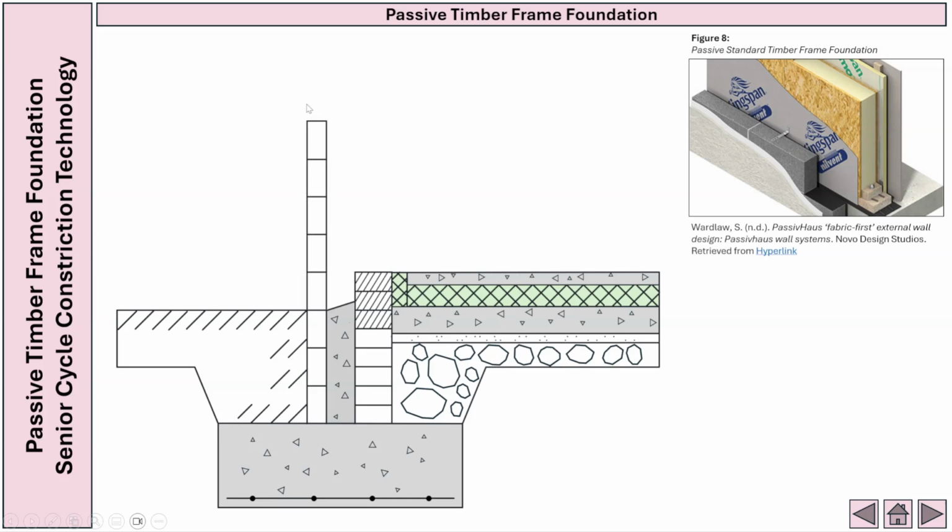On the left side here we have started our external leaf, and this is going to be our traditional concrete block outer leaf. Next, what we're going to do is put in our 50 millimeters of wood fibre board, and we're going to start this off by drawing it at the top of our second insulated block here. We can see that we also have our breather membrane just here as well.